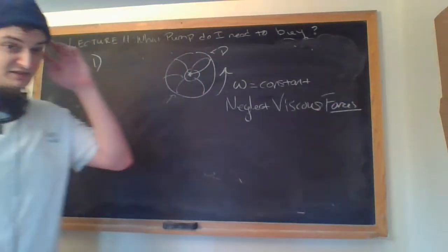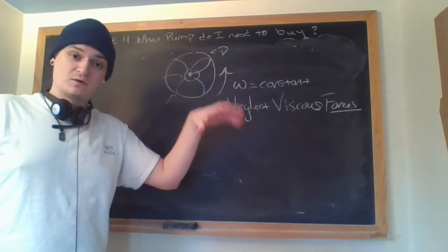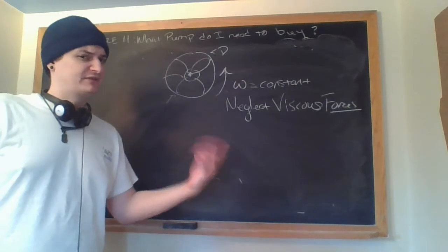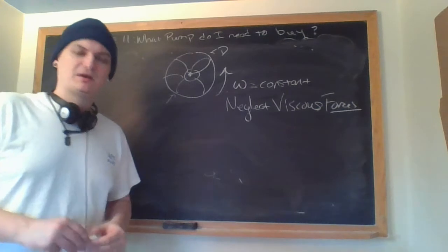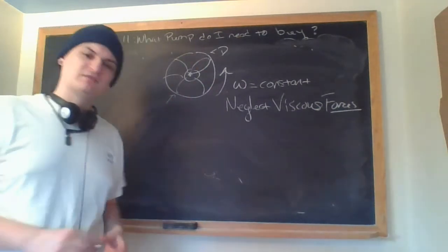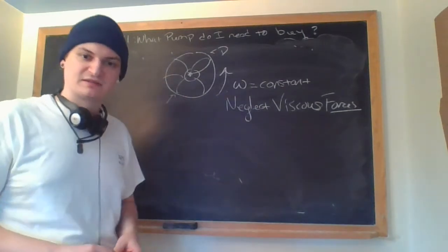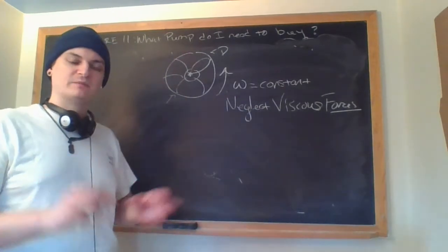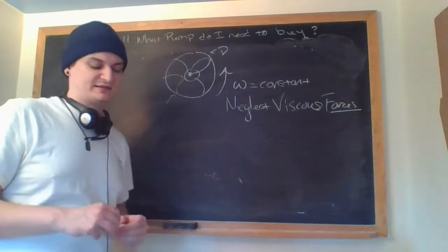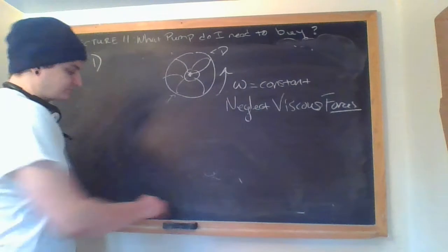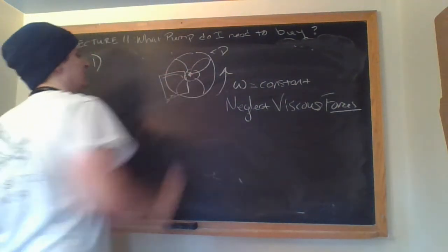the viscous forces in that entire analysis, because we had the sum of the torques that were happening. We didn't involve a viscous torque or any terms like that. Essentially we're saying all the fluid's moving so fast that the Reynolds number is really big, so I don't need to consider those viscous forces. All I need to model this flow are the Euler equations of motion, where viscosity goes to 0.